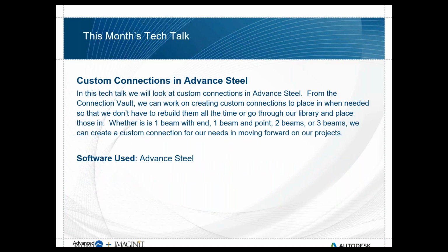In today's Tech Talk, we're going to be looking at custom connections in Advanced Steel. We're going to go a little bit above and beyond just the connections that you can work with through your connection vault in Advanced Steel. We can take those connections that we make and, through the library that's there, create custom connections that we want to use multiple times.